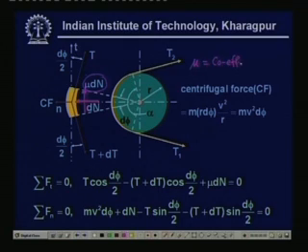coefficient of friction. So, mu dN is the frictional force acting onto this one, and here is the centrifugal force due to the motion of the belt. There is a centrifugal force that will be acting onto this belt segment, which has been given as a value Cf, and this value of Cf is computed over here.